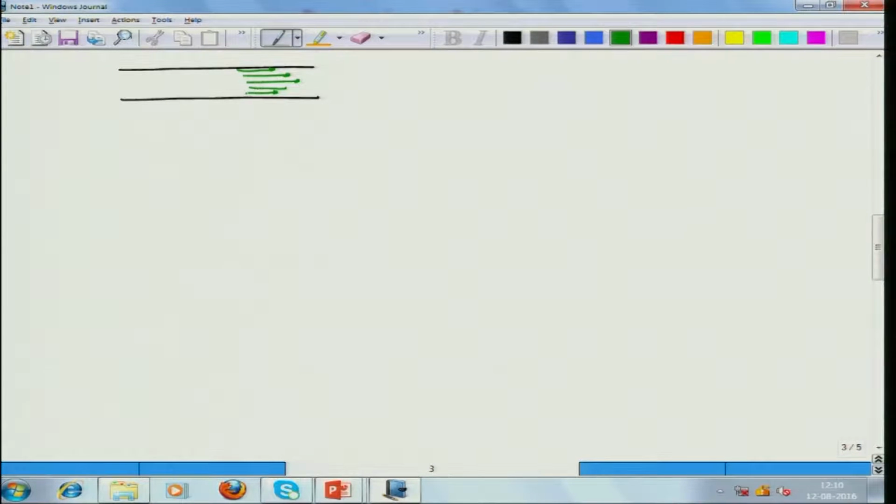Here, the velocity in the middle will be the highest. So this is the overall profile. Now this is more cumbersome to make use of, because you need to know the profile expression across this cross section, okay. And in this case what would be more useful is to find out the average velocity. So if we say this cross sectional area is AC, this would be your average velocity, okay.